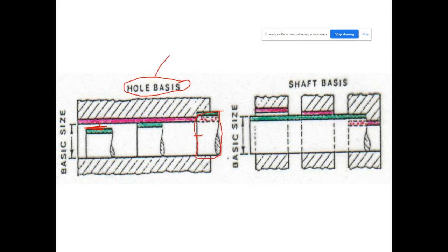This is very practical because we can adjust the milling machine or turning machine very precisely, and then set the size of the masculine feature to the correct order without any difficulty. But in shaft bases, the method is different. In shaft bases, to have the clearance between the masculine and feminine feature, we change the size of the feminine feature. Especially if the feminine feature is a hole, then in the market, you may not find a proper cutting tool to increase the diameter of the hole.